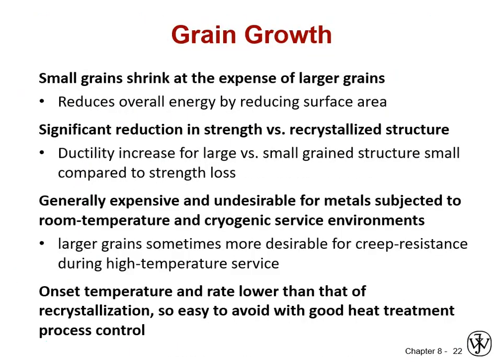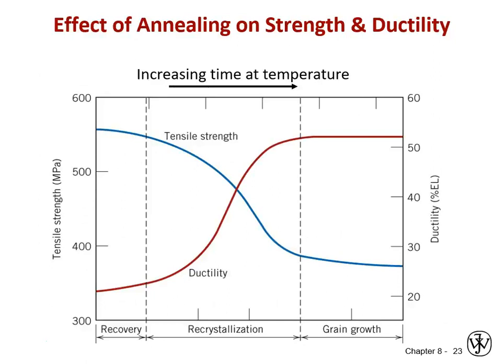So we are annealing the material, heating the material up for the purpose of letting the grain boundaries grow in density at the expense of our dislocations. So if I needed something that was less brittle, but still very strong, I might want to stop my annealing step somewhere towards the end of the recovery, where I may not have a lot of ductility, but I've still got a high strength. If I needed to go through another forming step with another heavy reduction in area, maybe to draw the wire finer or form an intricate part, I might go all the way towards the end of the recrystallization and stop just short of grain growth.